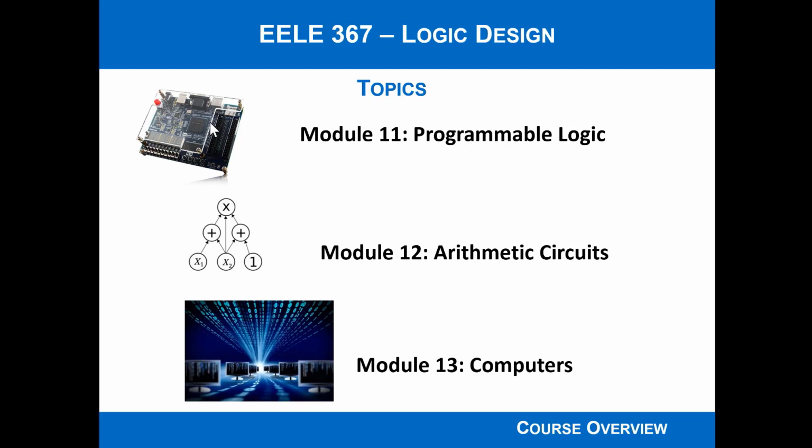So we actually go and look at what is an FPGA. And to do that, you have to kind of look at what was the history of programmable logic that led to the development of an FPGA. And once you get to that point, now you're sitting there going, okay, now I'm getting good at digital design, because I'm not just throwing VHDL down, hitting synthesize, and hoping it works. It's like I know where the gates are going. I know they're going into lookup tables on this FPGA, and I know what an FPGA is.